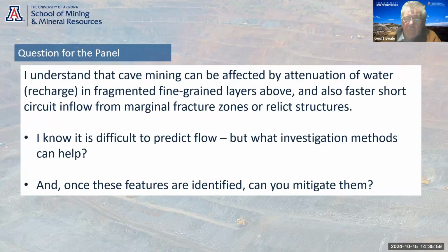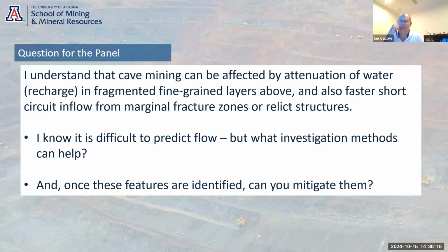A mine pit that went underground but wasn't originally designed as an underground had an unacceptably large surface water catchment, and we knew by the end of the wet season that every time it rained, we were going to have a mud rush underground. Whereas in the first two or three months of the wet season, not so much. Yeah, but that speaks back to the wet season aspect and also the surface water management.